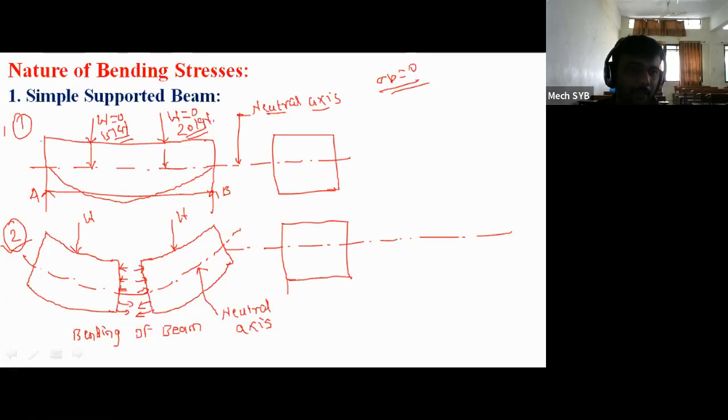बघा, figure number 1 is perfectly straight आहे, बरोबर आहे. And in figure number 2, the bending of the beam is taking place like this. Okay, and due to this bending of the beam, there is a possibility of bending stress, and that we have to calculate. But in addition to this bending stress calculation, this simply supported beam is subjected to tension as well as compression. And now we have to check where the beam is under tension and where the beam is under compression.